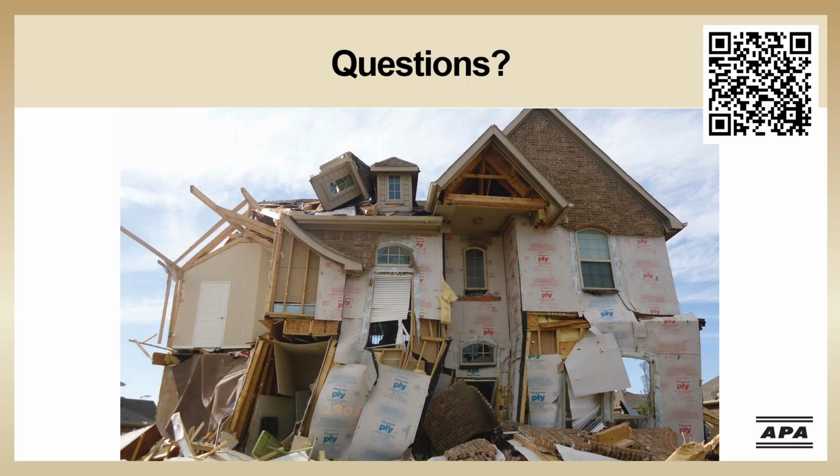We want to make sure there are enough fasteners to move that lateral load from the sheathing into the collector and then back out again. So 6 inches on center would definitely achieve that, since that's what's required if there was a panel edge at that location. If we're talking about engineered shear walls, I think it would make sense to use the same concept and just use the same fastener spacing as is required for the perimeter fasteners.